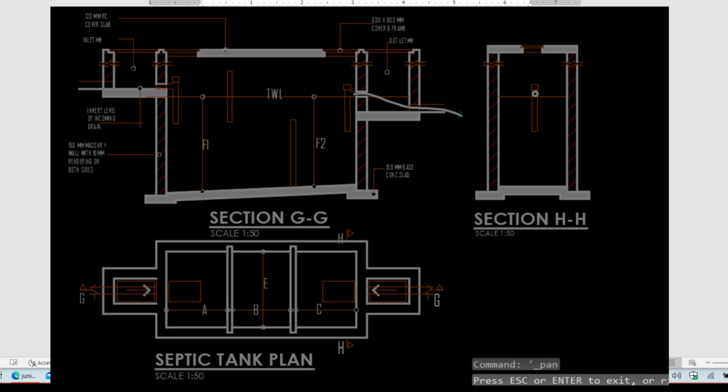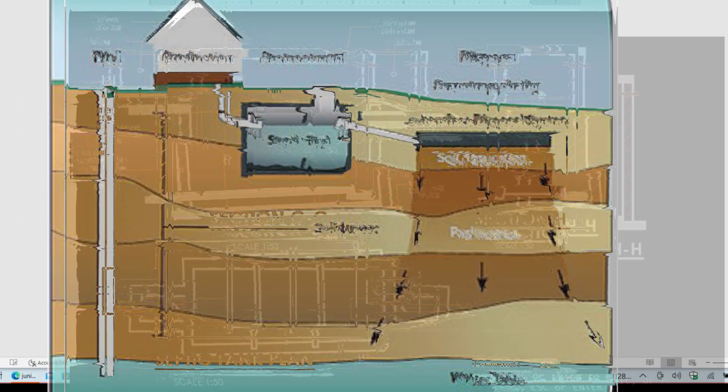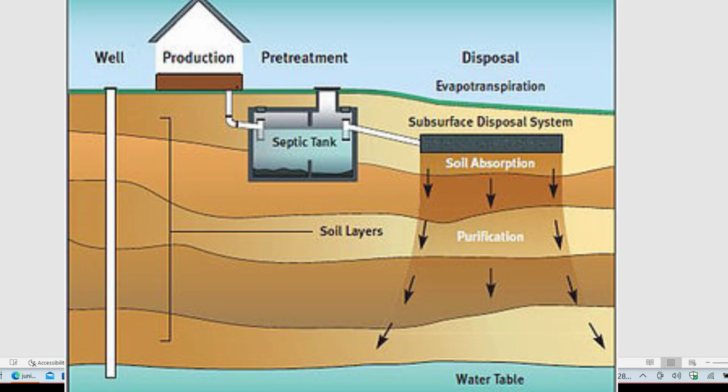So simply put, a septic tank can be defined as a primary sedimentation tank with a large detention time, 12 to 36 hours, against a period of 2 hours in an ordinary sedimentation tank. In unsewered rural and urban areas, septic tanks are suitable for the disposal of human waste, but sufficient water should be available. So this is a caution.